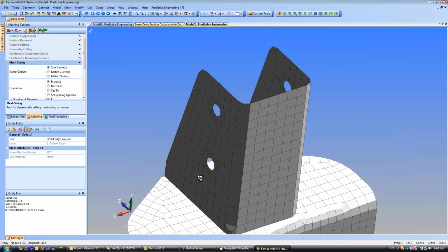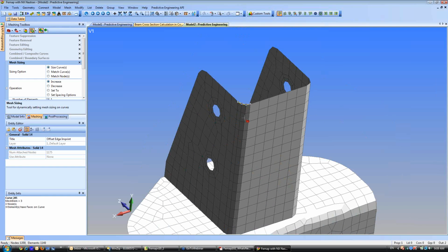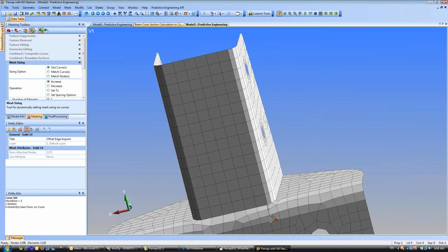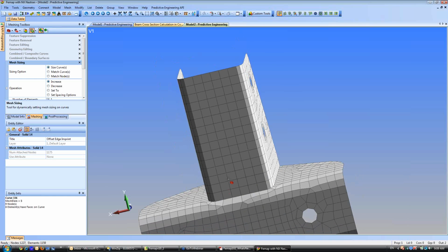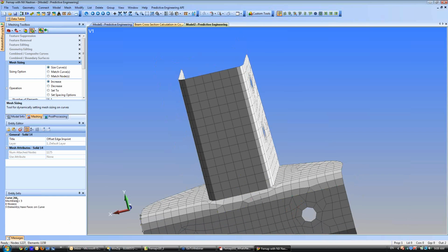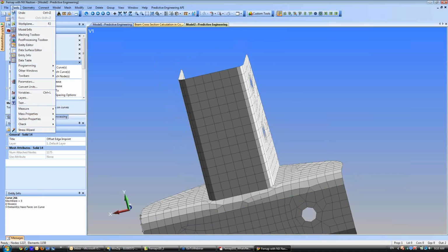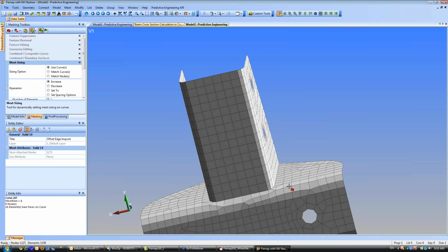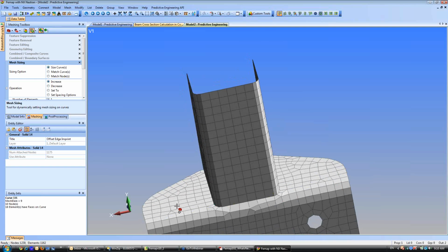And likewise, I can take this corner here and you can just sort of play with the meshing. I also like keeping the entity info pane on, that's under Tools, Entity Info, because when you're working on this, it'll echo. It'll tell you what your elements are doing. So there's 8, 9. You set that up like that, you can get a little bit better mesh quality.